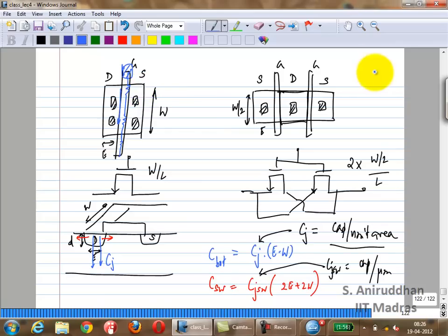There doesn't have to be current flowing through this. Is there a difference between this and this? Is there a difference between these two cases? There is no current flowing through it, right? What is the difference actually? Why? If you consider the gate capacitance, it becomes definitely more significant at higher frequencies, right? Because you are worried about the gate source capacitance.